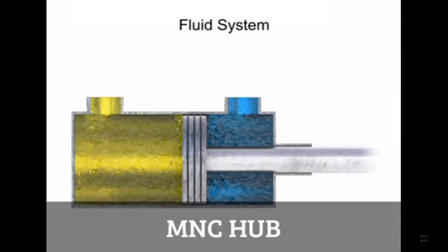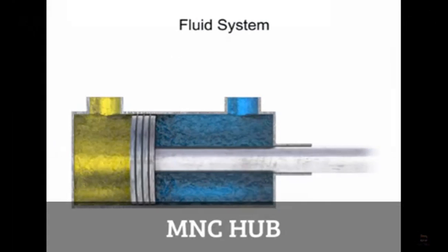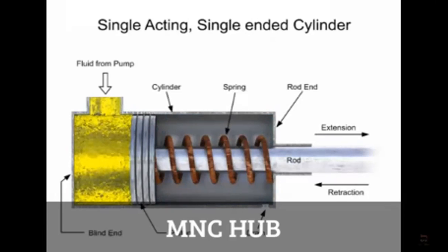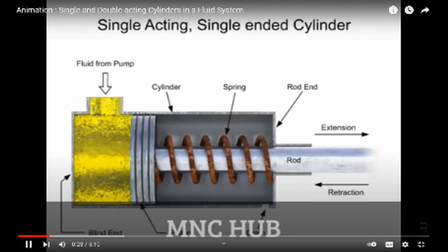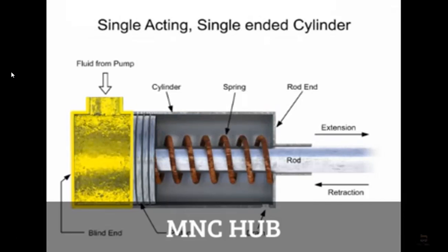Cylinder actuators deliver a linear push-pull motion via a rod and piston within a cylindrical tube. A single-acting cylinder is a cylinder in which the working fluid acts on only one side of the piston. The other side of the cylinder utilizes a mechanical load, springs, compressed air, other cylinders, or the momentum of a flywheel to push the piston back in the other direction.